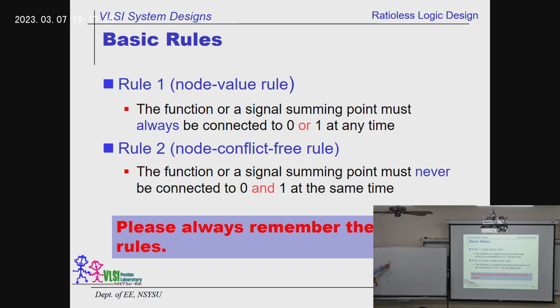See, this is 1, so this is turned on, right? And this is 1, this is turned on, right? So everybody's turned on. So what is the voltage here? You cannot determine it. I'll give you a more detailed analysis. When this is on, we have a current coming from the top, and since there is no other path, the current will go down to the ground as well. So we have the same I_on for everybody.